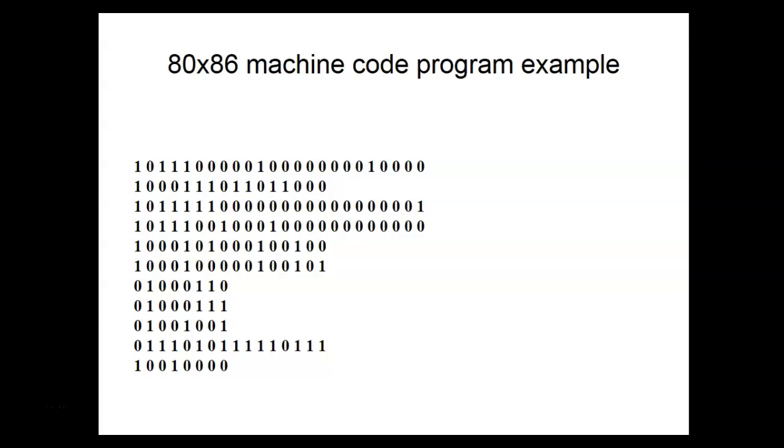An opcode is a code, but we call them operational codes. So this is a binary code, and when the processor goes into the fetch phase, whatever comes in from memory, it uses as an operational code. Then it switches into the execute phase and does what it was told to do, and then it switches back to the fetch phase. In the old days, that's the way processors ran: fetch, execute, fetch, execute, fetch, execute.